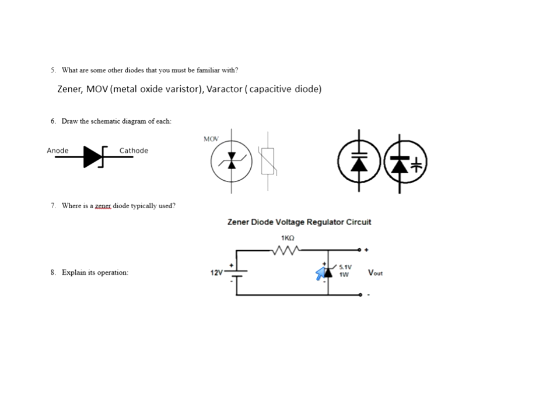It's always reverse biased. What does a Zener do? Explain its operation. The Zener is placed in parallel with the load that you need to regulate. And the Zener voltage across its terminals will regulate or hold the voltage steady across its anode and cathode.